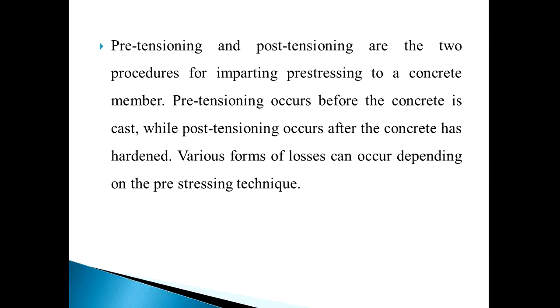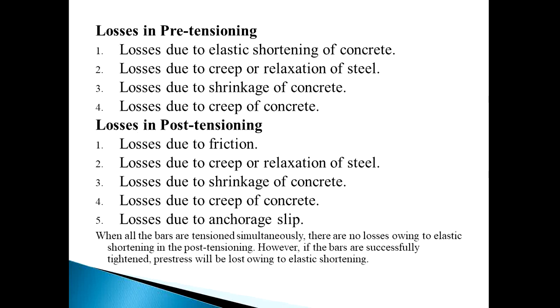Pre-tensioning and post-tensioning are the two procedures for imparting the pre-stressing to the concrete member. Pre-tensioning means the concrete is poured after the tensioning of the steel, and post-tensioning means the concrete is hardened before applying the tension on the steel. Basically, these losses are bifurcated into pre-tensioning and post-tensioning. Let us see one by one.